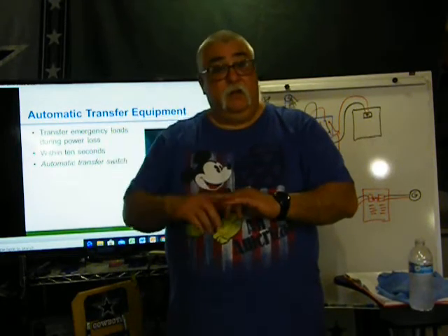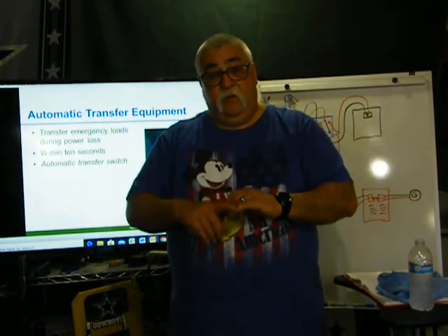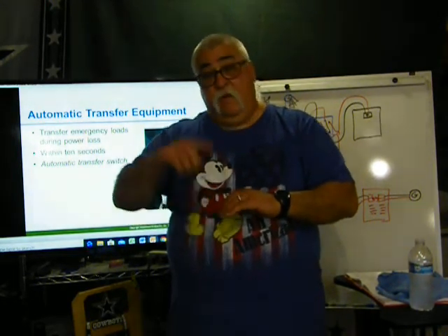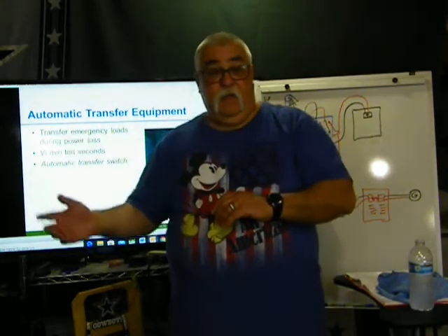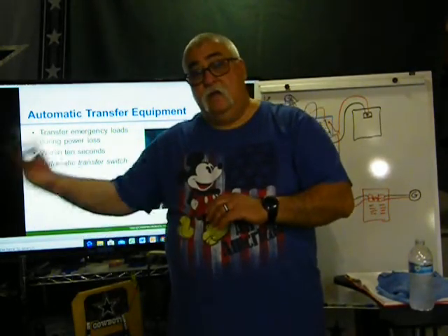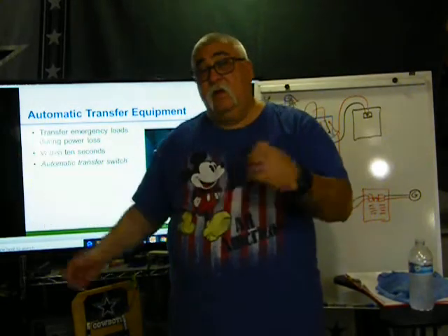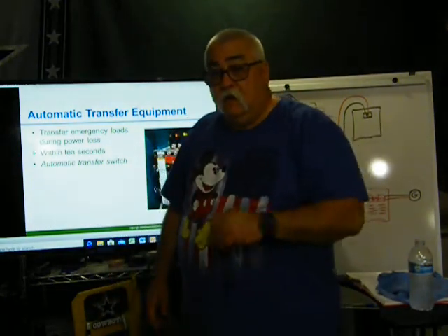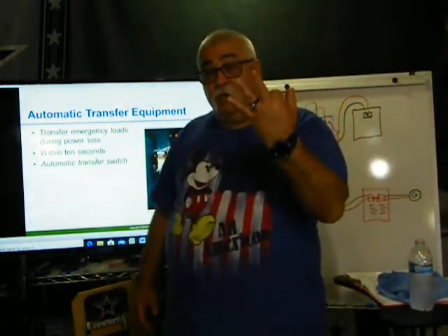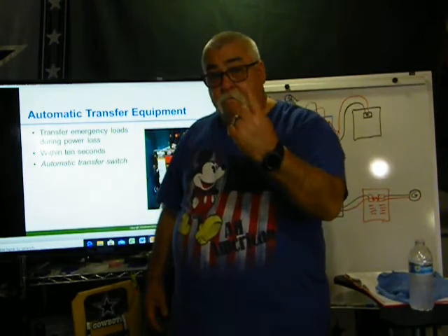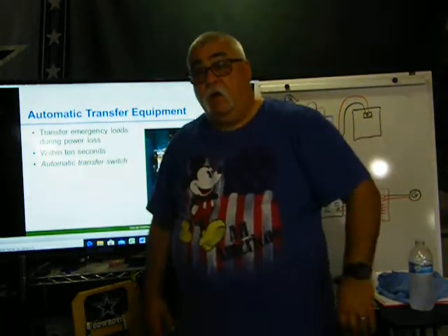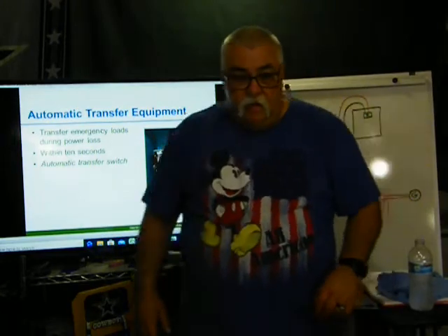And then I have another one on the fourth floor. It takes care of 4, 5, and 6. And then I have a separate one that does the motors separately, because the motors are separated from my power and my lighting. Okay, so now I've got 3 transfer switches run by 1 generator. Now you have to check all of them to make sure everything's running.